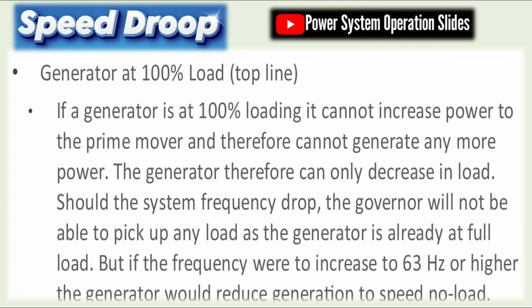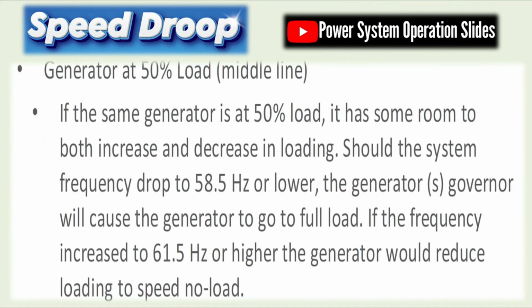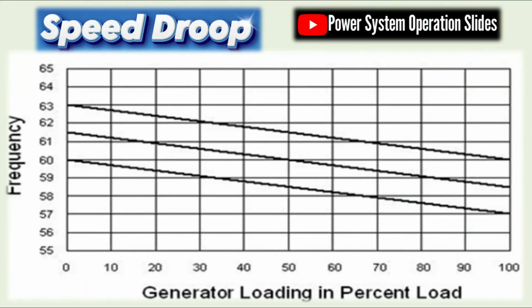By allowing a controlled deviation in speed relative to load changes, both the governor and speed droop work together to distribute power evenly and maintain the overall frequency stability of the grid. This dynamic modulation not only simplifies the operation when grids are interconnected but also enhances the reliability and resilience of the power system during transient disturbances or significant load fluctuations.